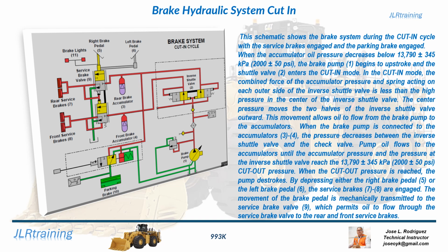By depressing either the right brake pedal, 5, or the left brake pedal, 6, the service brakes, 7, 8, are engaged. The movement of the brake pedal is mechanically transmitted to the service brake valve, 9, which permits oil to flow through the service brake valve to the rear and front service brakes.